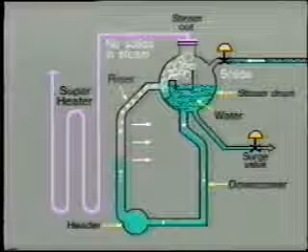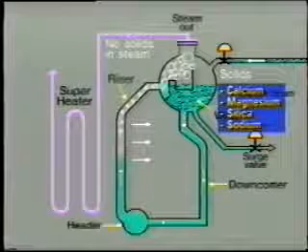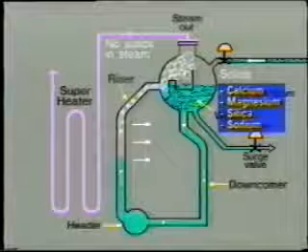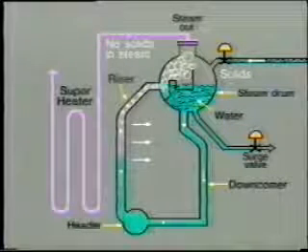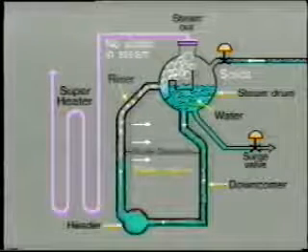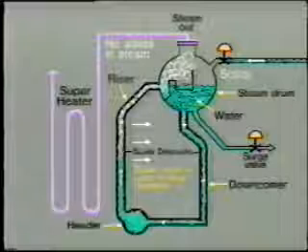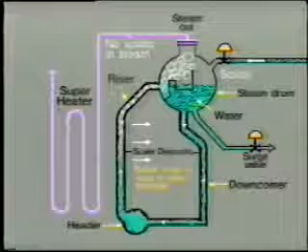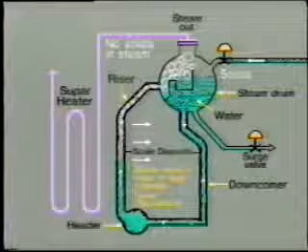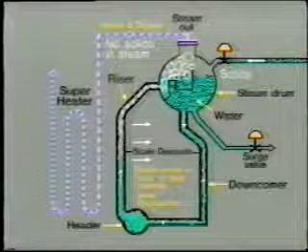a high value. These solids consist typically of calcium, magnesium, and silica or sodium, all of which are contained in the original makeup water. A high concentration of these solids can result in two problems for the boiler: deposits of hard scale inside the boiler tubes, with a resultant lack of heat transfer, and consequent overheating and damage to the tubes. Violent fluctuations in water level, with the possibility of some water passing over with the steam into the superheater and eventually the turbine.